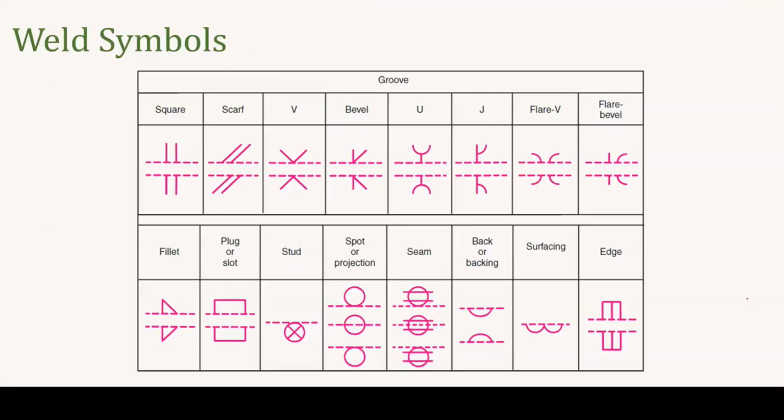Sir, where will these welding positions, 1G, 2G, be mentioned? Generally you will have a welding specification sheet. That means we will have the engineering drawing. Once we see that engineering drawing, we will come to know about the component. In that engineering drawing, they will put all these things. That means what we have seen, the positions, and the very important thing is weld symbols, right? They will represent this welding as symbols in the instruction sheet, that is nothing but the engineering drawing sheet.